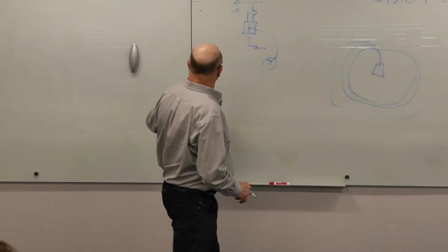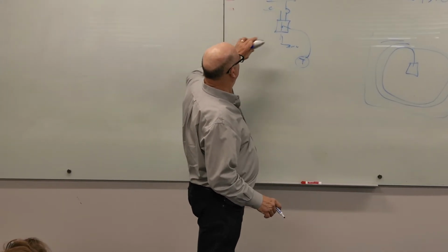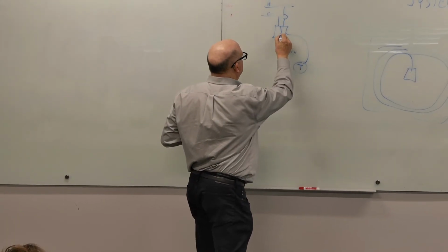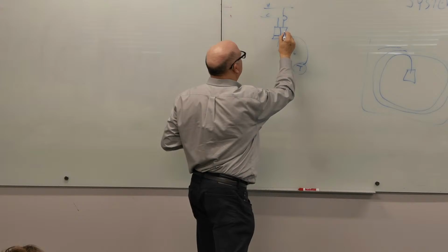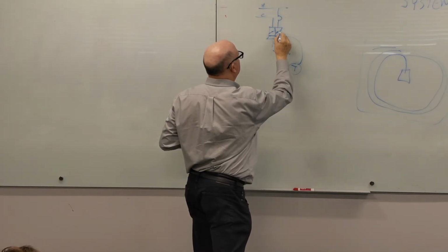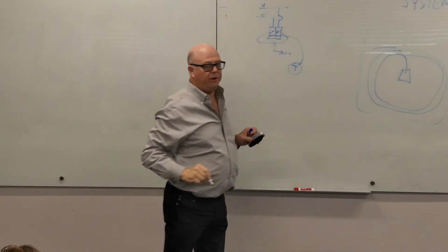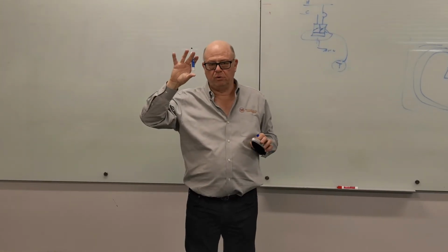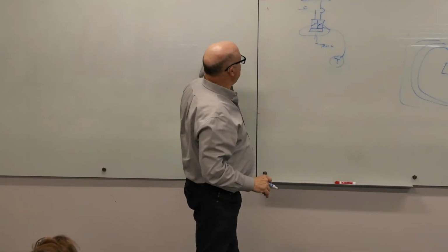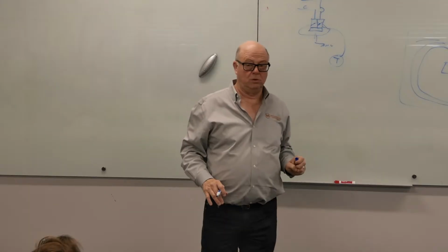They didn't radically change this, but what they did is, first of all, they put a line here and a plenum. They got an independent damper and another independent damper. They've got two actuators, typically one controller, but two actuators. And you could do anything you wanted with those two.